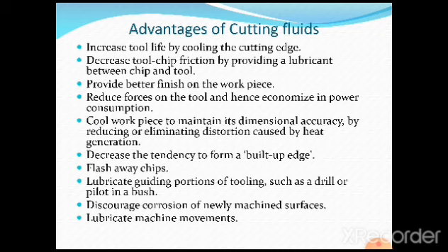Cool workpiece to maintain its dimensional accuracy by reducing or eliminating distortion caused by heat generation. Generally, if the cooling action is not given in the cutting zone, then the heat will be absorbed even by the workpiece. Thereby, there is every chance that the properties of the work material can also be changed because of the high heat generated. Decrease the tendency to form built-up edge. This I already told. Built-up edge is a false edge that is created on the cutting edge of a cutting tool due to continuous machining or cutting operation. This can be decreased because we are going to provide the continuous flow of a cutting fluid.